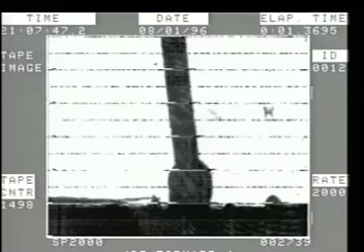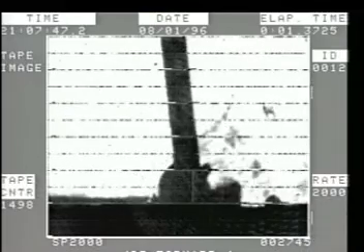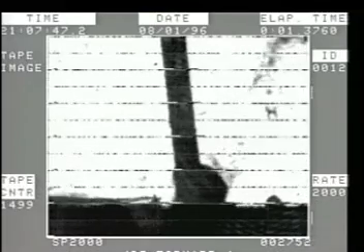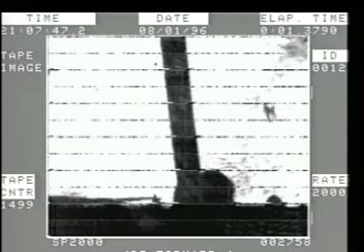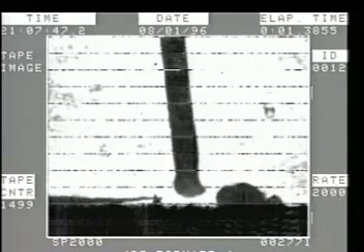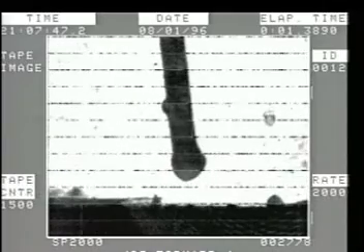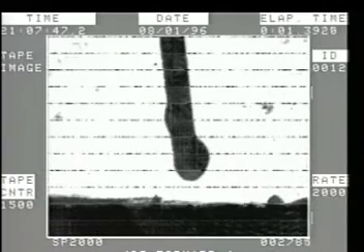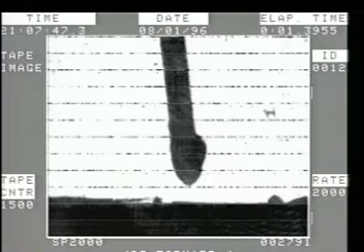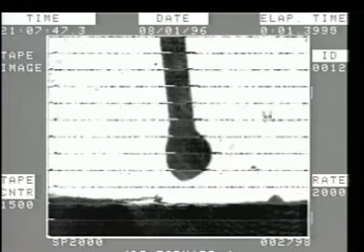You will see violent explosions as the arc actually shorts out. The current rises high to try to pinch the droplet off, but fusion occurs and the very large droplet is thrown out of the weld zone. This violence in the process accounts for the excessive spatter. The operating range of the globular transfer method is very wide.